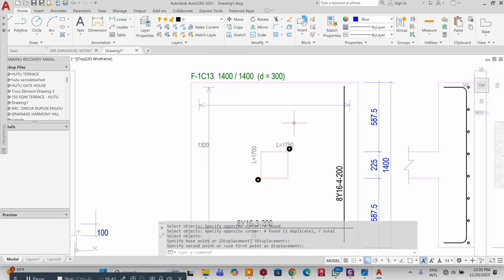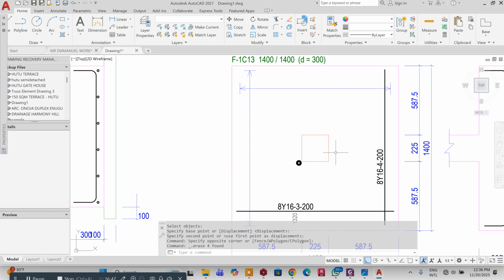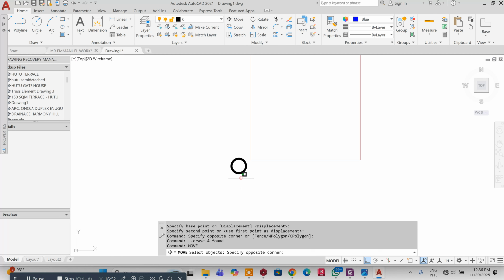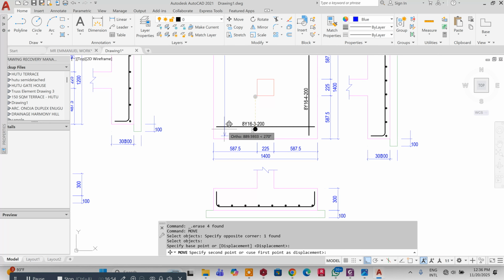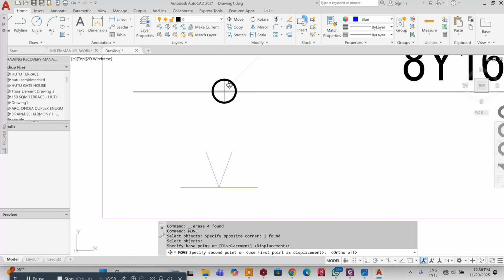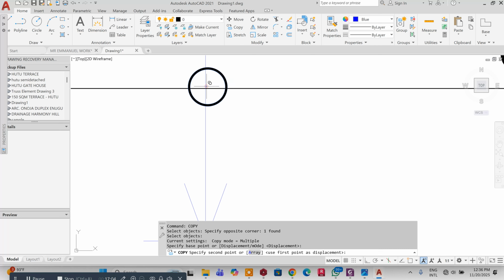No, it doesn't make sense, and sometimes the reinforcement may still be the same. So it's always advisable that you try to work on your footing sizes, because you are the structural engineer. Don't allow the software to be controlling you. You be in charge. Always be in charge.